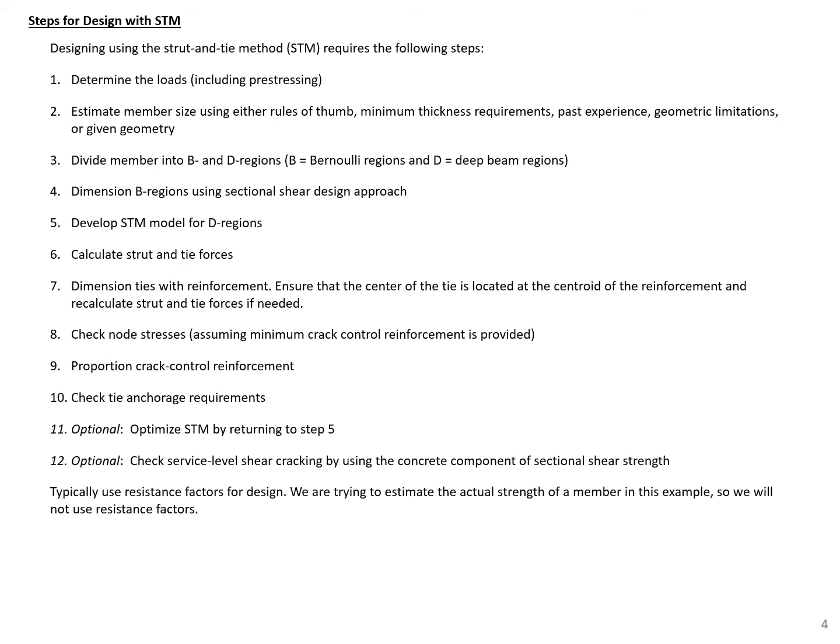Next, we're going to start our Strut-and-Tie method analysis. Shown here are the different steps that we'll do in a typical Strut-and-Tie method design. For our analysis, we will already have these first two steps completed. We already know our loads; those are given, and we have been given our member size. We've also been given the reinforcement, so we'll do an analysis using the Strut-and-Tie method. But anyway, these are the 12 steps that we'll typically use for the Strut-and-Tie method, and we'll work through them on the following slides.